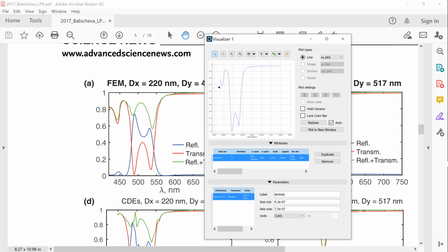As I mentioned in the first video, in no way do we pretend to be comparing the methods or software packages. There is some discrepancy in the results that can be explained by slight differences in the material functions. Besides that, we can further improve the FDTD simulation by using a finer mesh. This completes the 10th video and our tutorial on the Lumerical package.